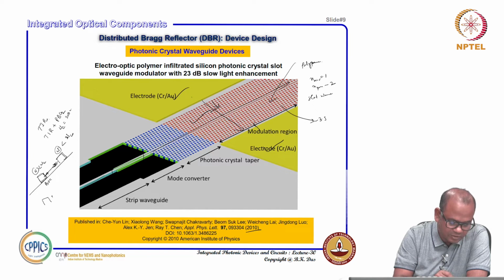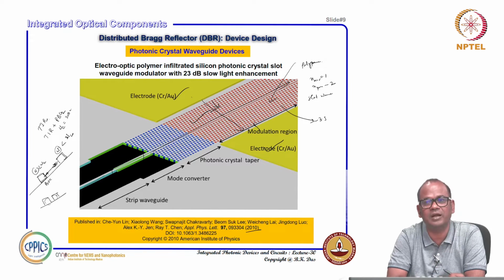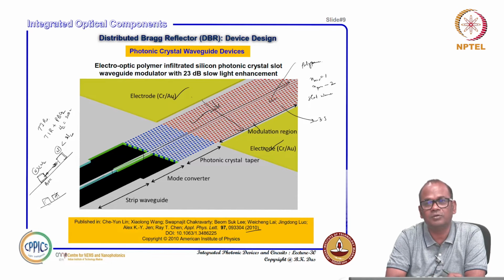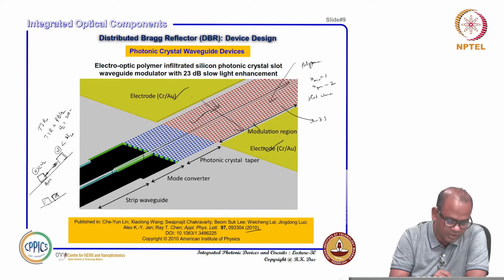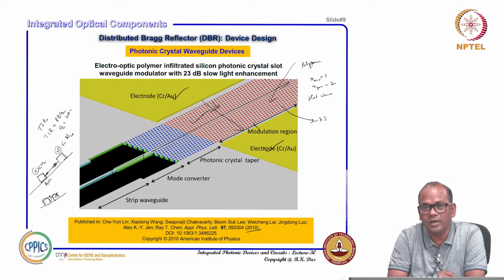Combined, they can confine light together. You can expect a guided mode. But in that case, the electric field inside the so-called rib region will be lower, and it will be enhanced in the gap just to follow the boundary condition.